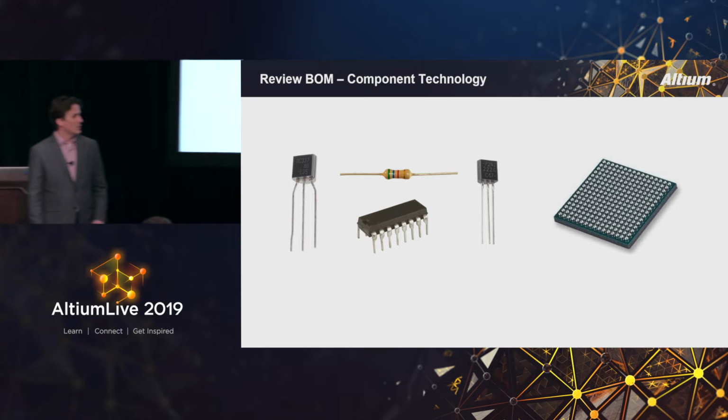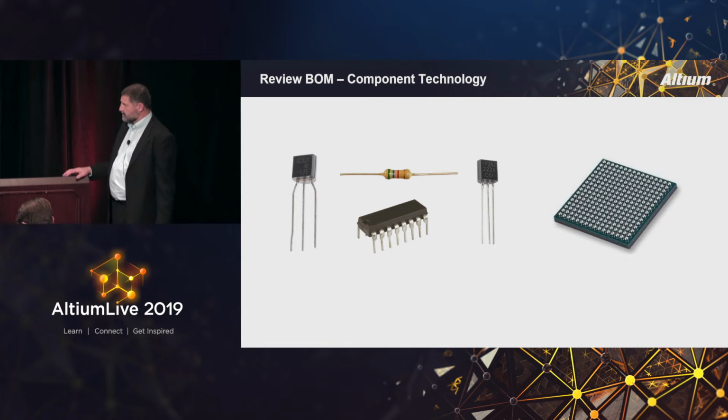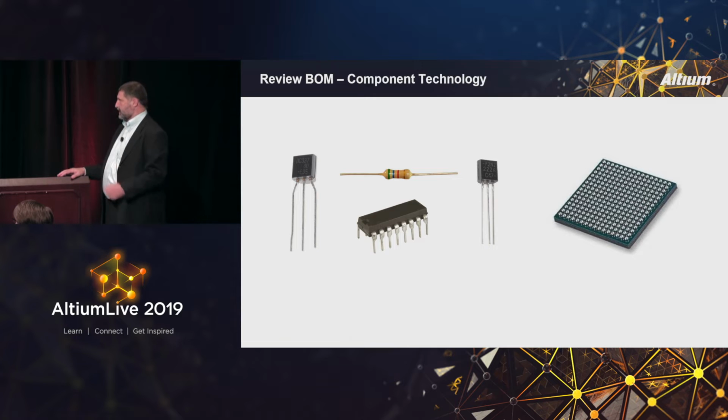So the components that are on your schematic are going to drive your assembly costs. If we have a high pin count BGA, it's going to drive the layer count up typically. It's going to force us to use more layers often. Not always, but usually, a high pin count BGA is going to drive that layer count up because we have to escape out of it.